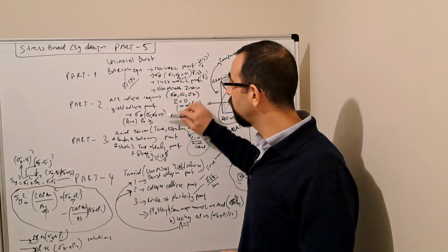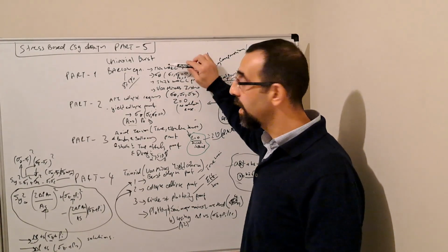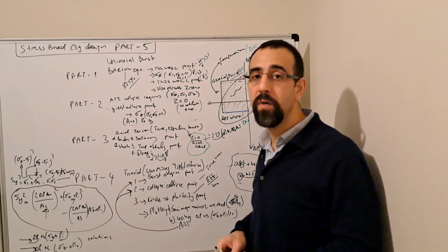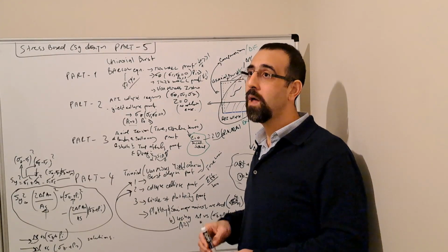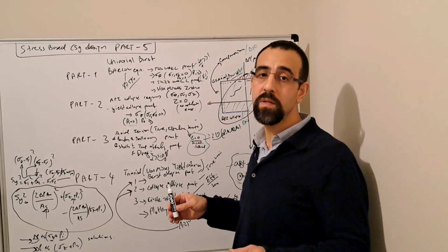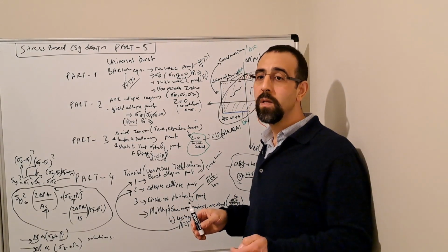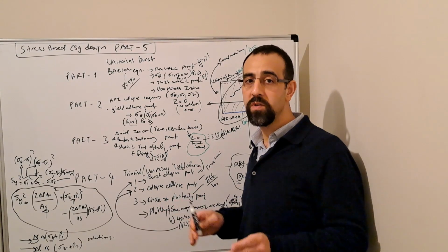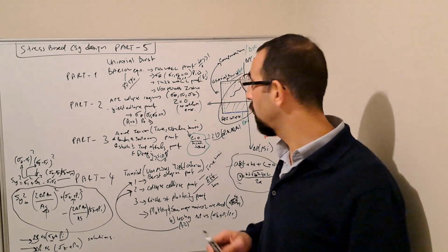If you remember, for the other API collapse regimes, like the elastic, transition, or plastic regimes, those regions were based on some physical specimen tests. Therefore, there were some limits on the diameter over thickness ratio, showing how each region transitions to another region.